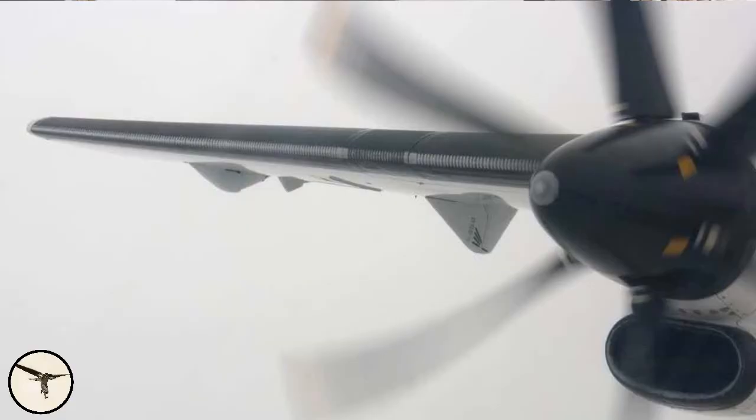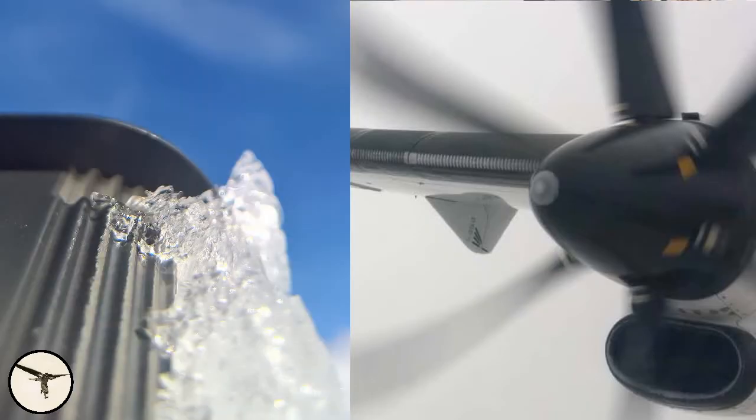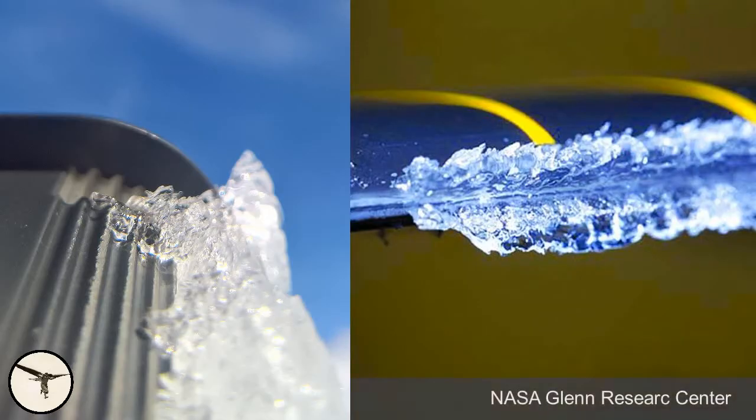Small drops freeze quickly when they hit an object. They form rime ice, which is white. Large drops need more time to freeze and tend to drag along the surface as it freezes. This results in clear ice, and it can build up rapidly. A mix of large and small drops may result in horn ice, which can result in a huge increase in drag.